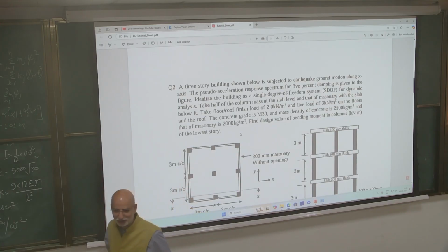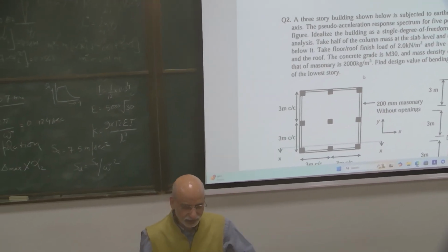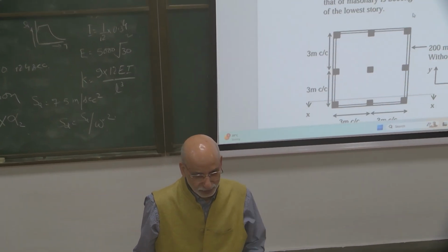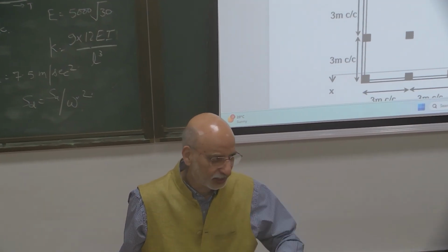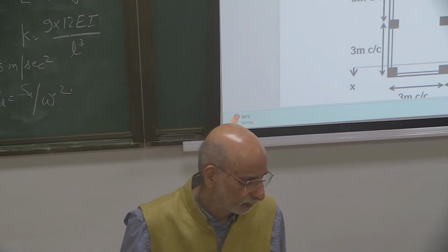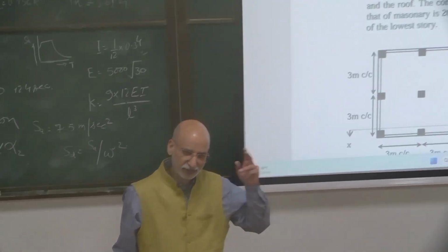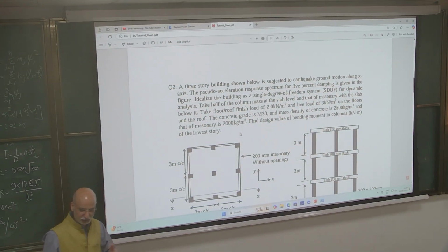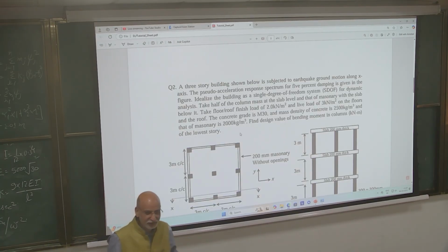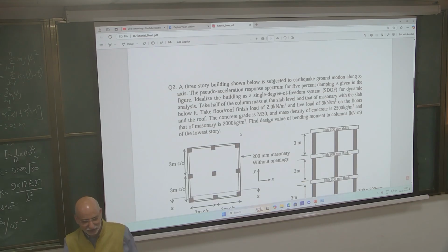By hand solution, you take a larger problem and do it. Hand solution gives an insight into the problem. With the help of a computer, you can do any size of problem very quickly. But to get an understanding, if you do it by hand, you get an insight into what exactly is happening. So rather than solving the characteristic equation of mass and stiffness, finding the eigenvalue, then the corresponding eigenvector, and then combining, you can convert it into an equivalent smaller problem. That is the idealization I mentioned here. And you can do it very fast. A 3x3 size you can do very fast.